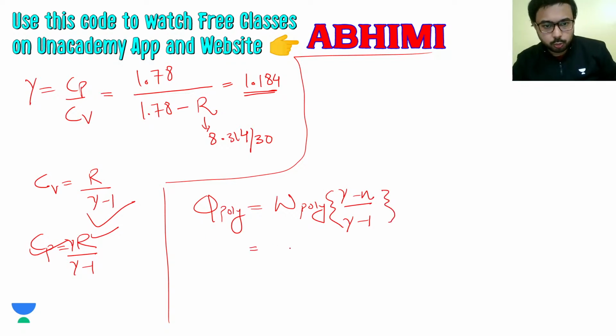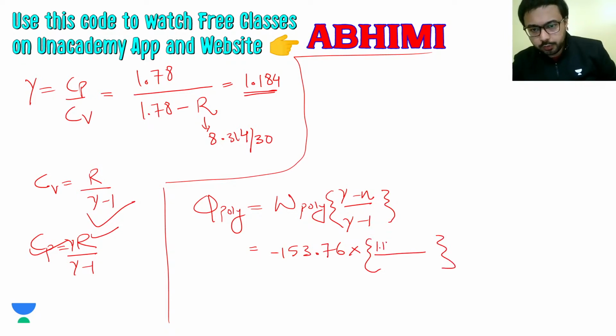So W polytropic is minus 153.76, and gamma minus n, gamma is 1.184 minus 1.2, divided by 1.184 minus 1.